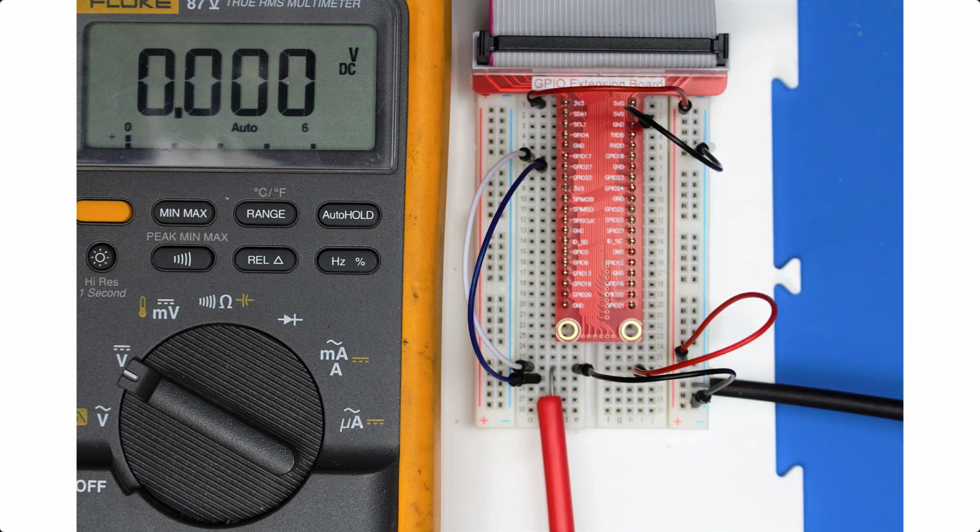You should now have the information that you need in order to test the pull-down resistor. With the pull-down resistor, make the same measurements that you made with the pull-up resistor, and you'll notice that you utilize the jumper wire that is connected to positive in order to trigger that switch to the on position. So go ahead and set up your meter and trigger the pull-down resistor.